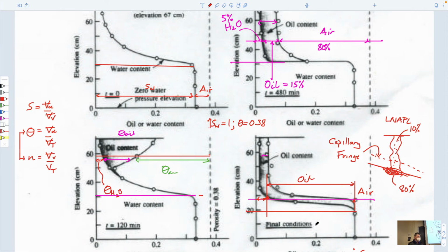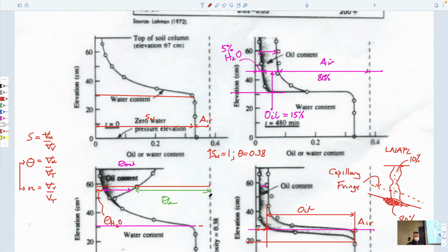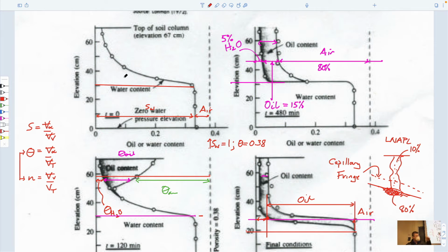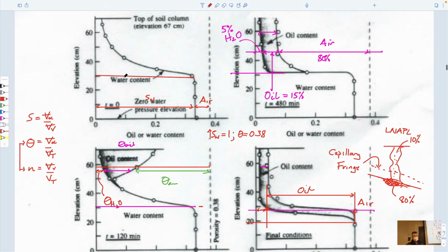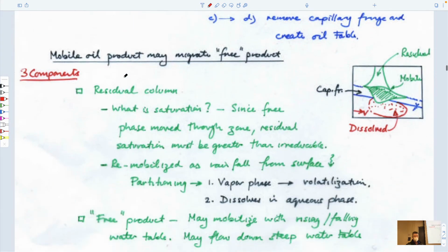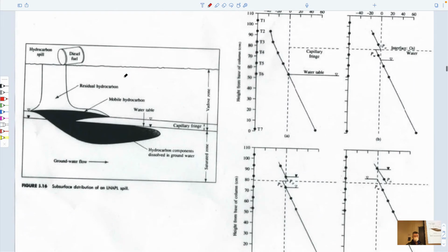And so you'd take a long, tall, graduated cylinder, 4 inches in diameter, pack it with soil, dump some stuff in the top, and make sure there's a place for the water to get out at the bottom to allow that to occur. Then just allow it to compress, and measure the relative saturations with elevation, maybe by excavating the column, removing the material, and sampling it to see how much fluid you have in what proportions in each of the parts.